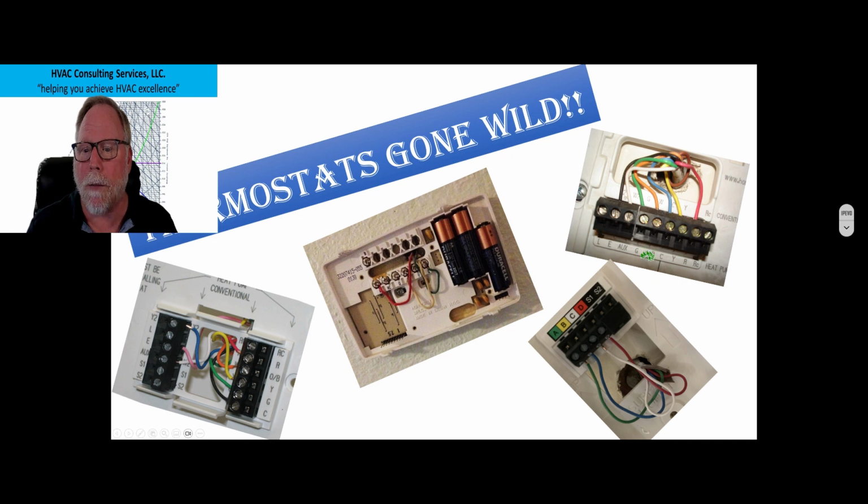And you see there O/B? Well, that O/B means that this thermostat can work with either a heat pump that energizes in the heating or in the cooling for the reversing valve. You will configure that inside the thermostat configuration menu or dip switch, and then you will hook up here to O/B. So this O/B will energize the reversing valve depending on what you've got it set for, energizing in the heating or cooling.